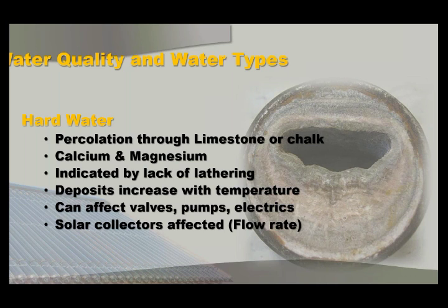So it really is a factor when thinking about the design of the system, and it can affect all sorts of things: pumps, electrics, valves, pipes themselves. That faded picture in the background is of an actual pipe, and that's a limescale buildup inside the pipe. Besides the flow rate, all kinds of other issues come from that.